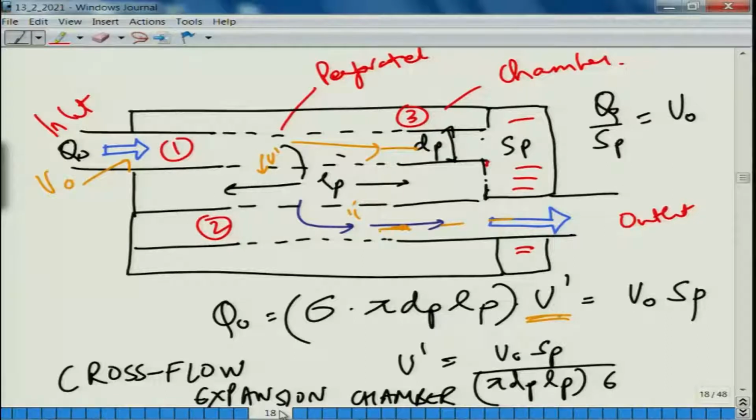Whenever you have a cross flow element, that necessarily means that you must have this kind of system where you have 3 interacting ducts. So, there are basically 2 perforated pipes. For simplicity, I have assumed that the perforated section is a common section between the 2 pipes through which the flow happens, and surrounding that is a jacket or annular region which houses these pipes. So, the idea is that the flow has to go through the pipes and come to the other pipe. As a result, we must have at least 3 interacting ducts.